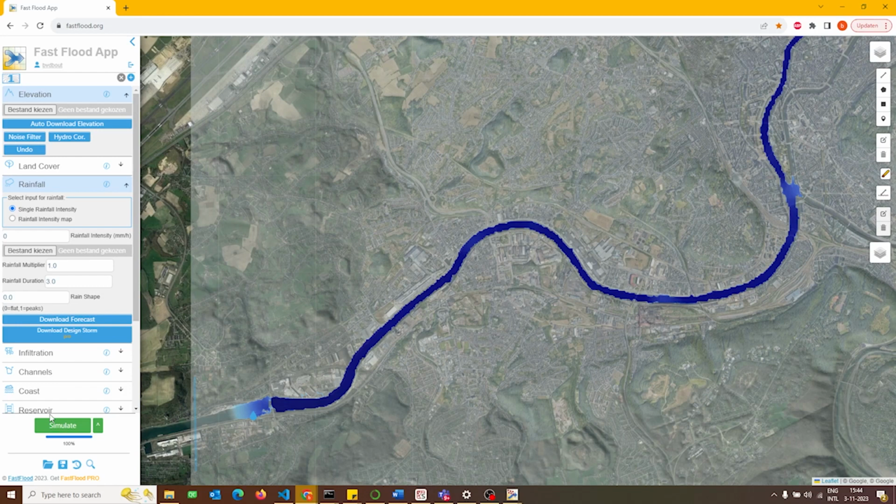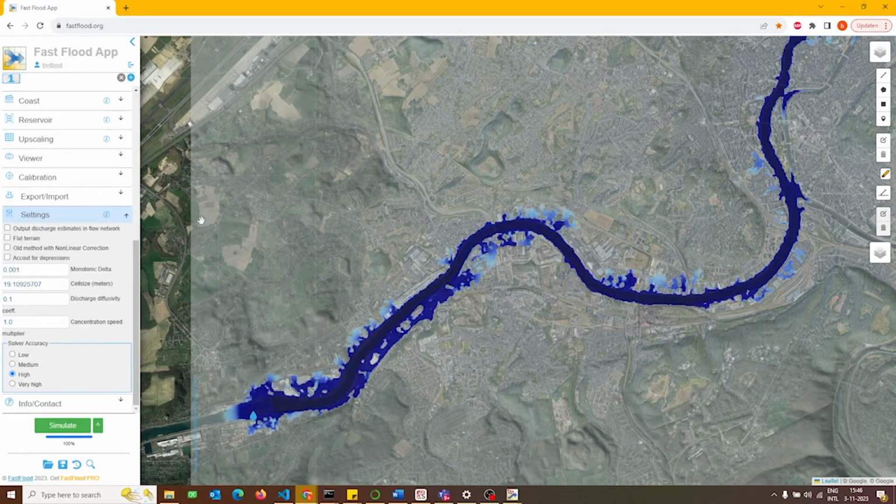But especially for these kinds of river systems, bathymetry data can be needed, and you sometimes have to provide your own elevation datasets to do good modeling. For now here, this is working reasonably well, and we should see that if we increase the discharge by quite an amount, we can actually see our flood behavior starting. And as you can see, when significantly increasing the discharge, we start to see the flood behavior that we would expect.